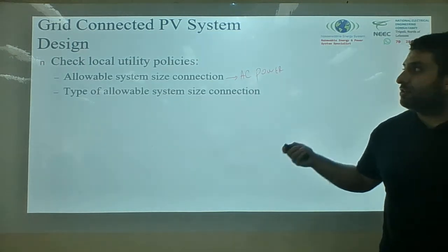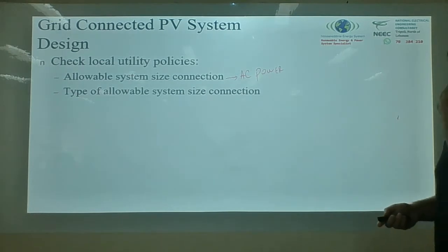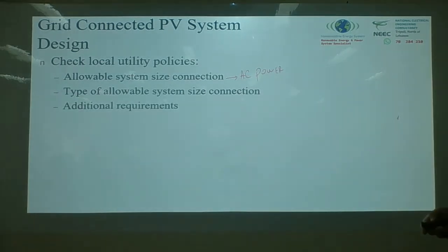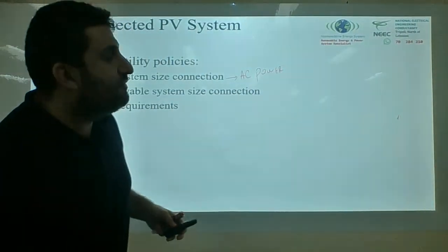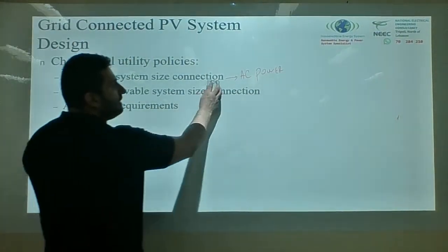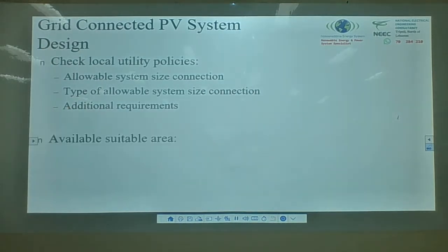Then the type of allowable system connection: is 3-phase or single phase required? They might have some sort of additional requirement. So it's very important to check the utility in your country or your area before you go ahead.